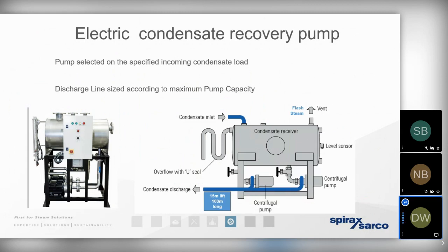The more of that hot water we can recover back to the boiler house, the less energy we need to raise steam, but the more responsively we're raising steam, the less chemicals we need to add to the feed water, meaning we need to perform far, far less of that blowdown. So of course that means that we get less carryover, less foaming, less scaling, and drier steam being produced.